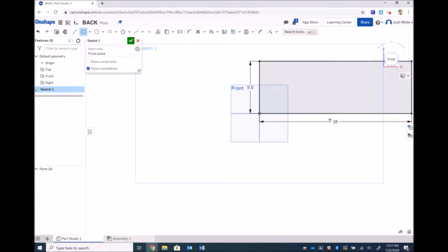Now, 5.5 inches is not on the drawing that you just recently saw, so that is an error on my part, and I'm sorry for that. Last video we talked about all of our 1 inch dimensions actually being 3/4 of an inch. All of our by 6 dimensions are actually 5.5 inches. And then we cut to length 16 inches on our miter saw.